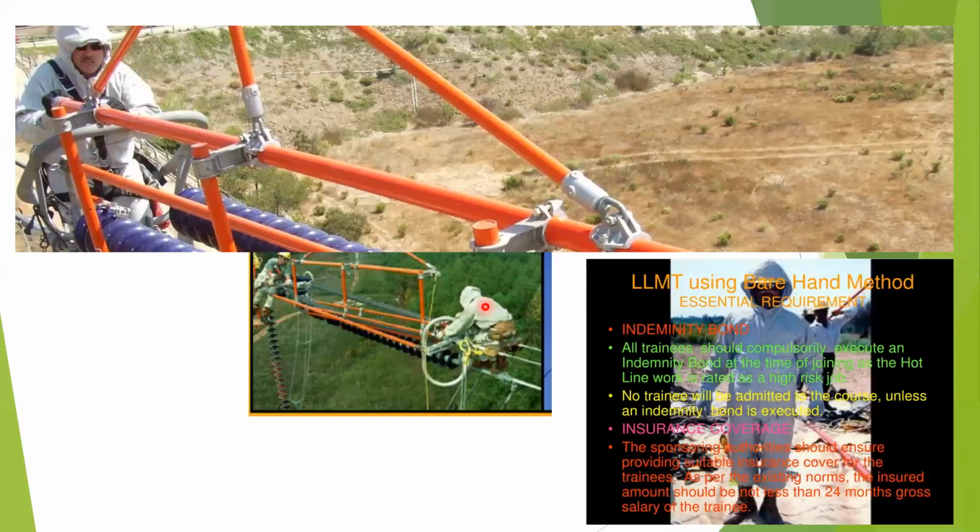So now this man is not doing bare hand operations, he's at the dead end, that means the tower end. This man is doing the bare hand operations, he is touching the 780 kV. So when you go with this kit and hook onto the conductor at that potential, you hear the sound of 100 frequency.